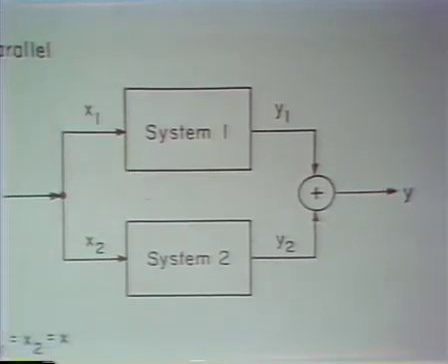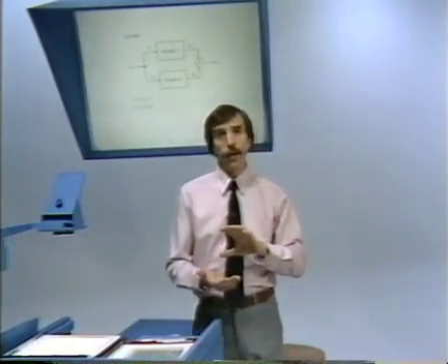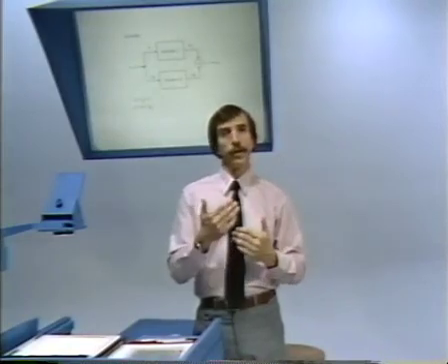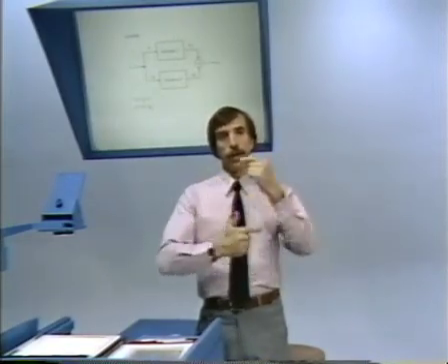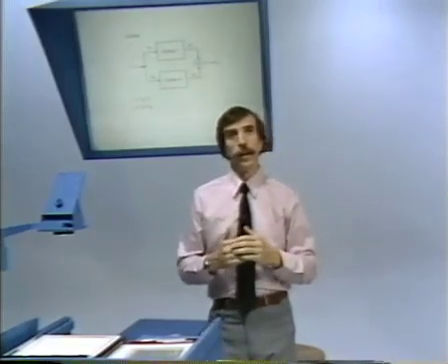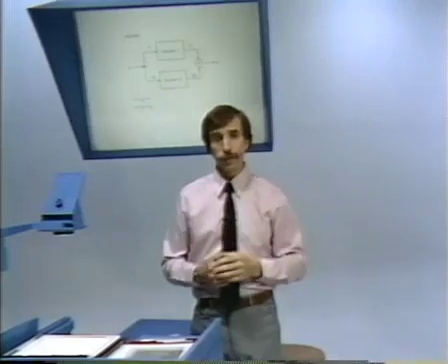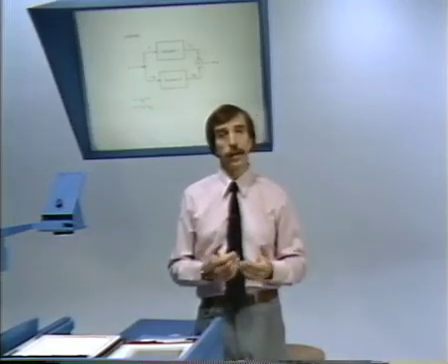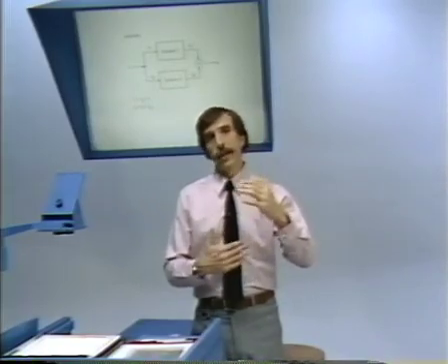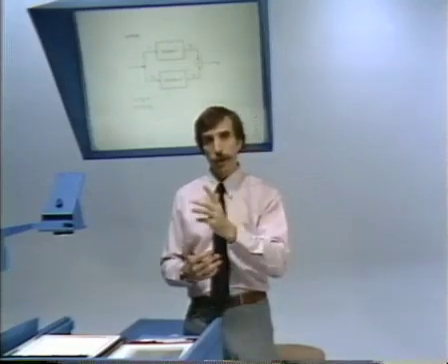Now, in this particular case, in contrast to a cascade, no matter what the systems are, it turns out that for a parallel combination, the order in which they're put in parallel doesn't matter; the overall transformation is independent of the order. And of course, that follows from the fact that we're simply adding up outputs, and the outputs can be added in any order because addition doesn't care in which order you're adding things up.